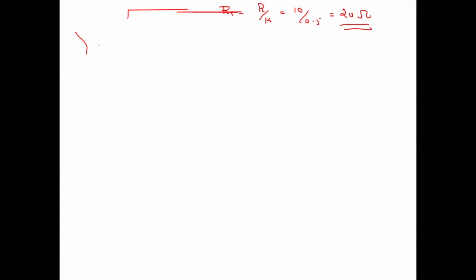So we already learned that in Fourier series, any waveform I can write in terms of DC component and AC components. Here, using that Fourier series analysis, the output voltage we write like K into Vs. This is the DC component, average value, and rest harmonics.